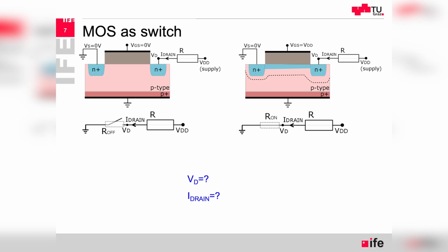And then the on resistance will of course depend on the doping levels of the materials, both N and P-type. It will depend on the technological properties at the gate, the thickness of the gate, the material of the gate oxide and polysilicon above, and of course the geometrical size of the transistor.